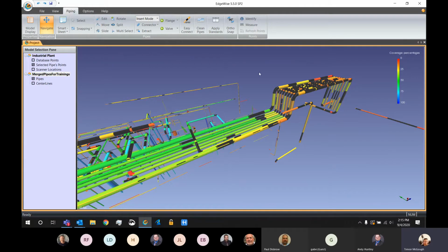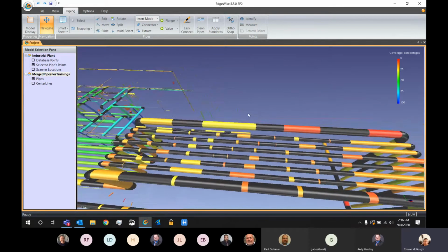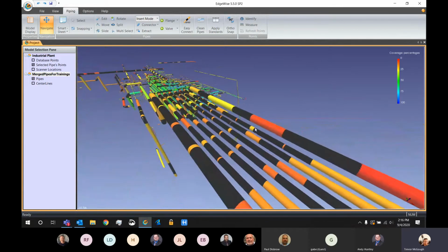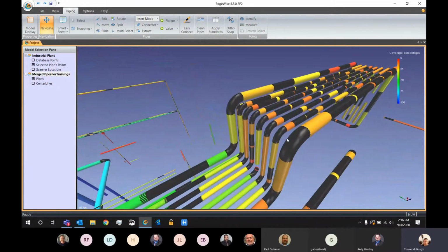So there you can see in black, that's everything the software just did. All those black straight connections right there, connecting up my pipe runs, as well as our first round of elbow connections. Everything right there is going to be default 1.5 bend radius degree elbows.